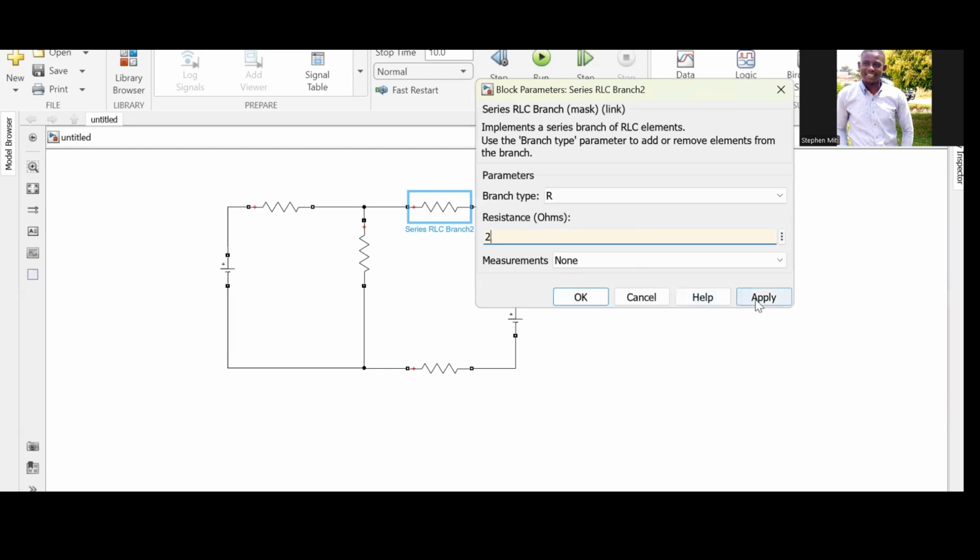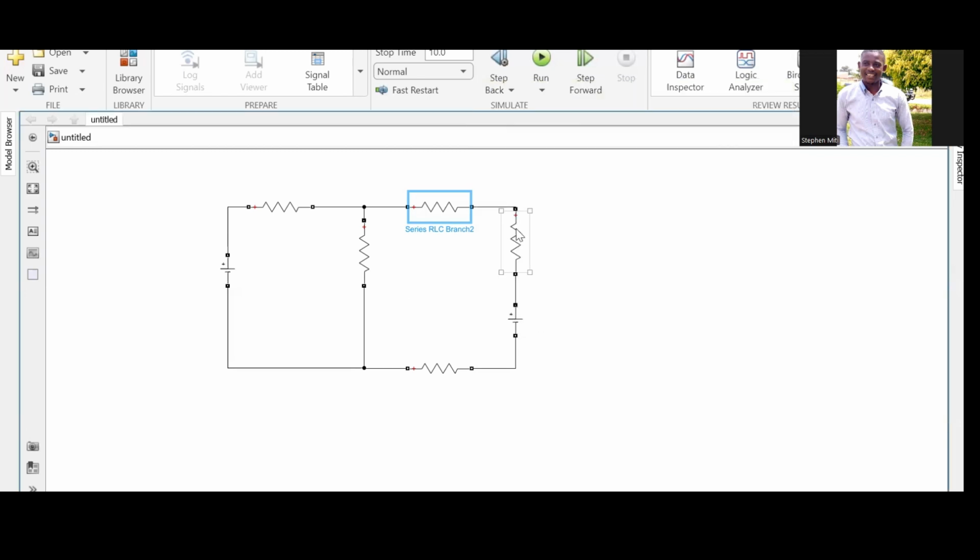Yep. So this is a 2 ohm resistor. Okay, now remember, you said this resistor was in parallel with a current source, right? So I've used what's called source transformation. With source transformation, I can use a voltage source instead of the DC current source. So you can easily connect your resistor and the transformed voltage source in series.